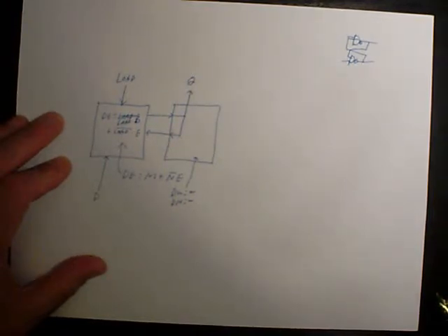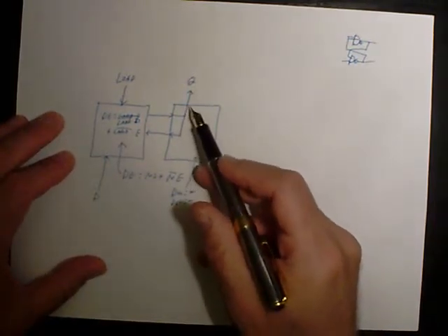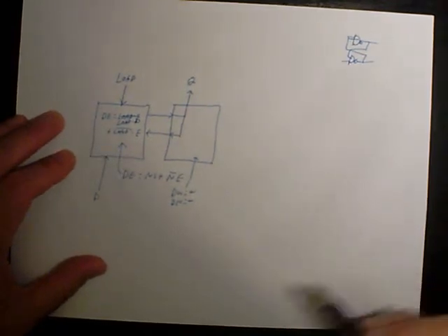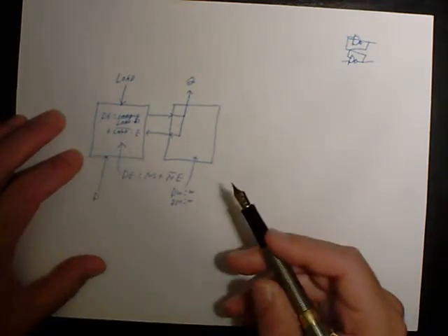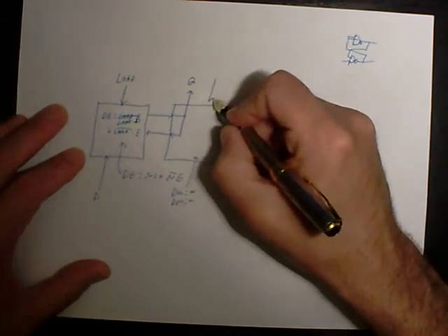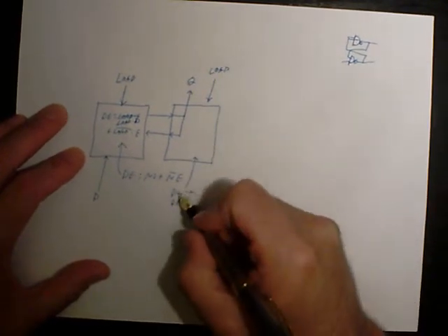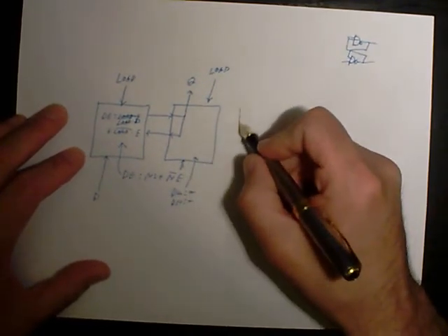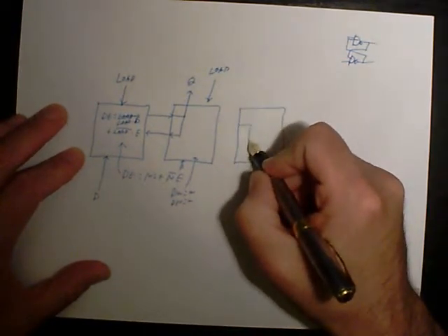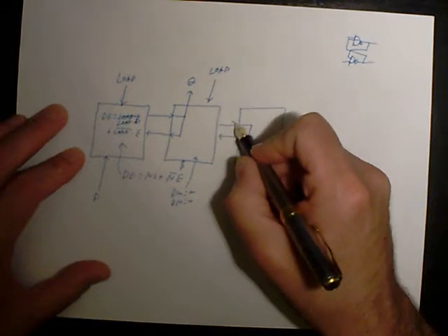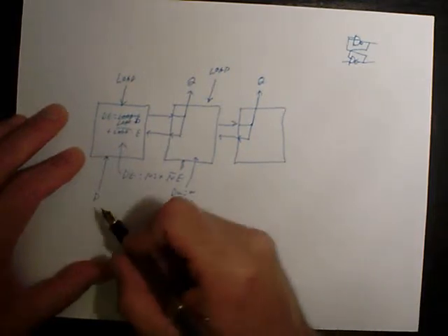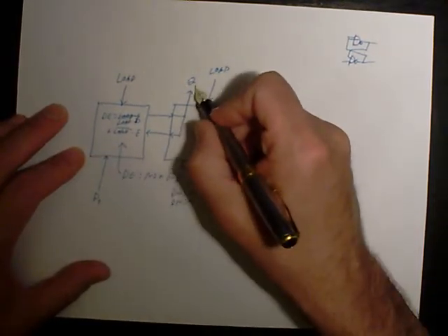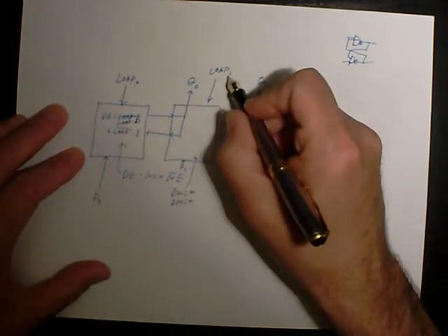Well, if we wanted to implement a 2-bit latch, we don't need another two cells because in fact this cell is only using the northern output and the western side, and this left cell of a 2-bit latch does not need the northern output or anything on the west. So we could also put a load line into here, put a D bit into the south, put another recirculate cell over here, send this out to Q, and now we can call this D0, D1, Q0, Q1, load 0, load 1.